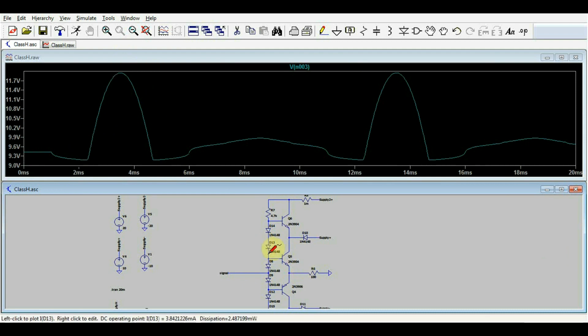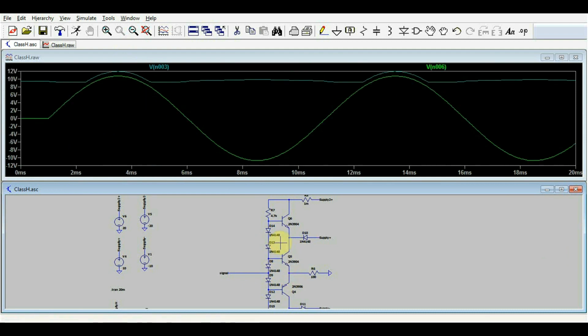And this voltage increase is proportional to our input signal. So we can see that the supply voltage, when we exceed a certain threshold, ends up rising proportionally to our signal. We no longer have the jump between two extreme voltages. And this sort of linear variation of the supply voltage keeps the output signal unaffected.